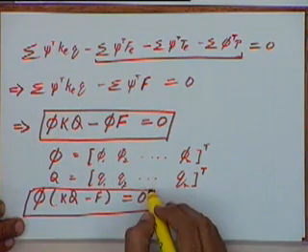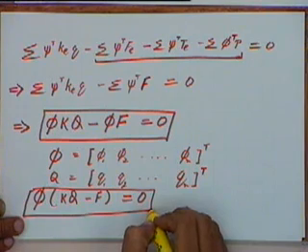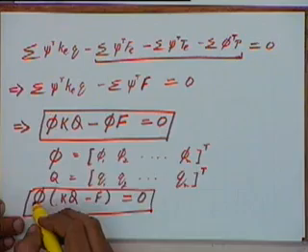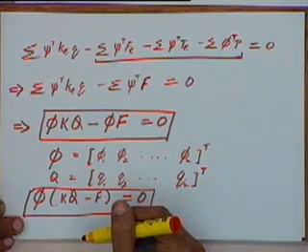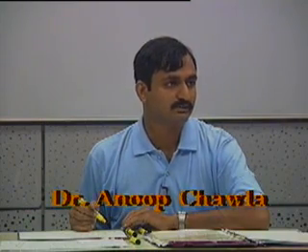So this equation we can use for solving for q. If it has to be satisfied for all values of phi, we can essentially say Kq is equal to F and then attach the boundary conditions to that. If we attach the boundary conditions, we will come back to the same equations as we had with the Rayleigh-Ritz method. So essentially we will see that whether we use the Rayleigh-Ritz method or the Galerkin's approach, the final equations will be the same.